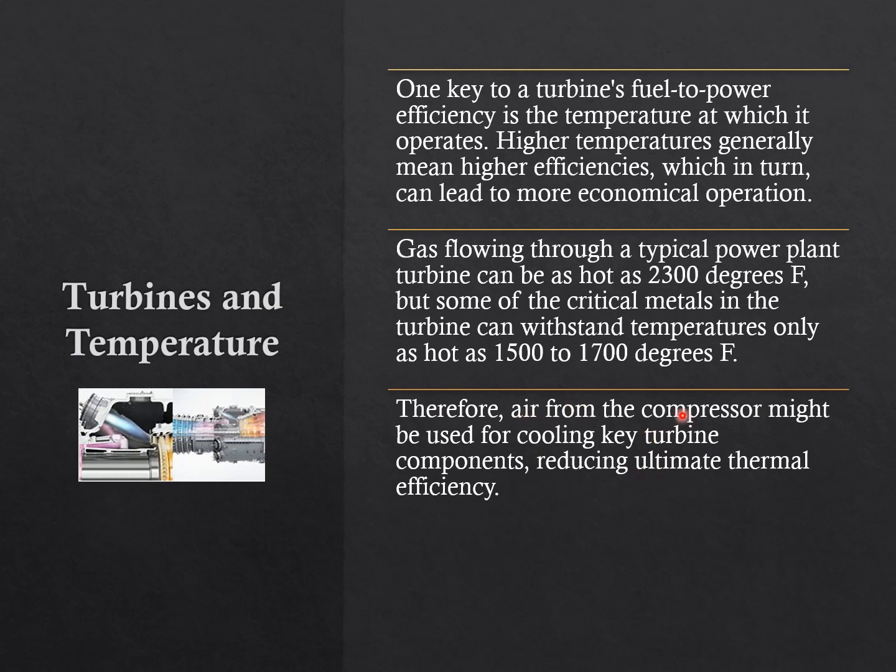The air temperature and the temperature of the system mix and reduce the temperature to where your turbine metal blades can stand, and of course the metal compartments can stand. You can see the temperature transfer and the temperature equilibrium, bringing a very high temperature down to what it can stand. That is completely assisted and helped by the air coming in from your compressor.